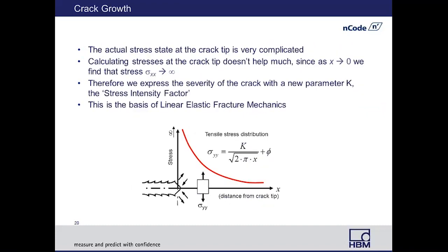Crack growth is actually something fairly complicated when you look at the stresses that are happening around the tip of the crack. These stresses, if you think about it, as you go to the tip of the crack, will approach infinity, and it does make it difficult to characterize that accurately. So what we're going to do is make use of a method called linear elastic fracture mechanics, and what we will be doing is expressing the severity of the crack with the parameter K.